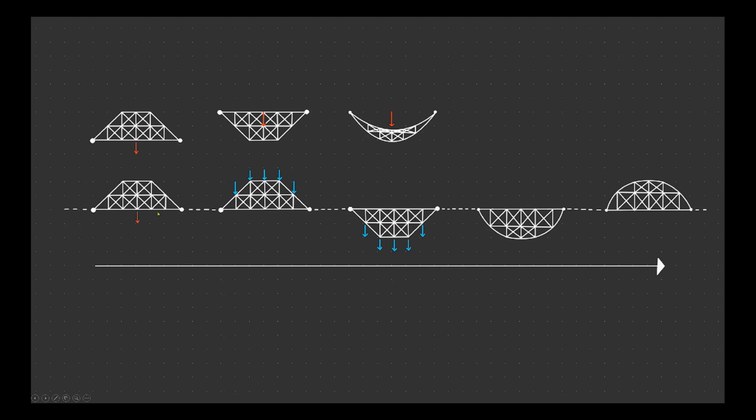First of all, forces should be converted to equilibrium forces that hang from the arch of the bridge. If not, the bridge rod will approach the arches, which is not desirable. After converting the forces, we can hang the bridge upside down. We can see the deformation and mirror it back. This makes one iteration. These pictures are exaggerated, so the code makes hundreds of iterations on average to find the optimal bridge shape. This is the basic logic behind our optimization part.